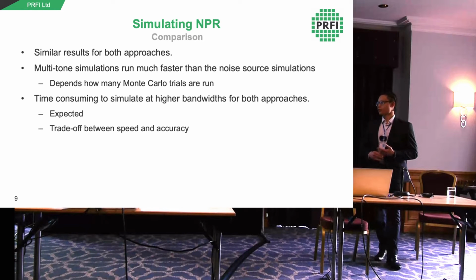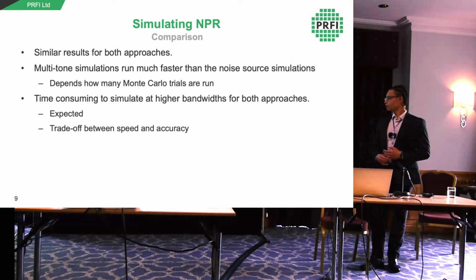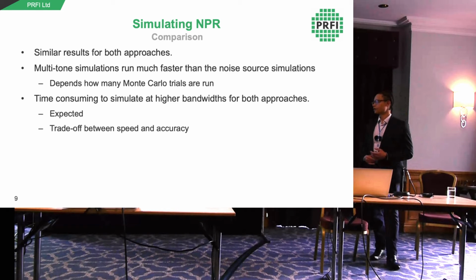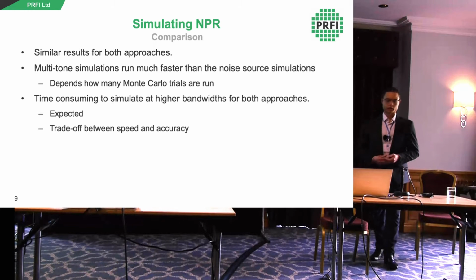That was also the case for the PDKs that we used in the EM models, but it's possible that might not always be the case. And as you'd expect, it was time consuming to simulate at higher bandwidths for both approaches. So you have a trade-off between speed and accuracy, whether you take that by adjusting the simulation settings or by adjusting your schematic, maybe converting some of those EM blocks to PDK elements. But you can't have both.